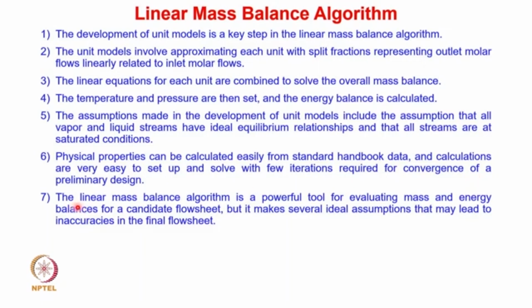And the last point here is the linear mass balance algorithm is a powerful tool for evaluating mass and energy balances for candidate flow sheet, but it makes several ideal assumptions that may lead to inaccuracies in the final flow sheet. But anyway, once this preliminary flow sheet is obtained, then we can refine this mass and energy balance equations and then come up with the final design.